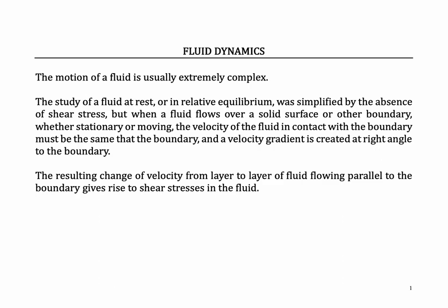Fluid dynamics. The motion of a fluid is usually extremely complex. The study of a fluid at rest or in relative equilibrium was simplified by the absence of shear stress, but when a fluid flows over a solid surface or other boundary, whether stationary or moving, the velocity of the fluid in contact with the boundary must be the same as that of the boundary, and a velocity gradient is created at right angle to the boundary. The resulting change of velocity from layer to layer of fluid flowing parallel to the boundary gives rise to shear stresses in the fluid.